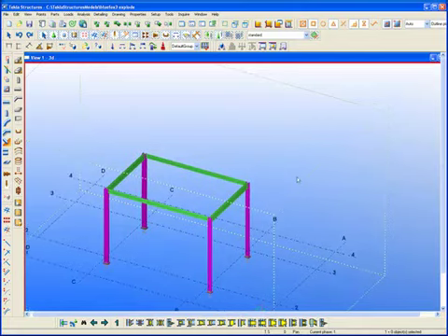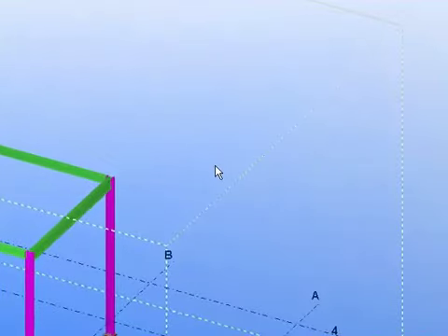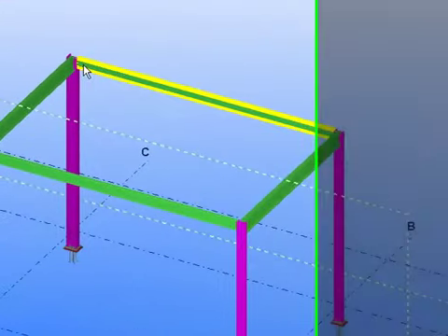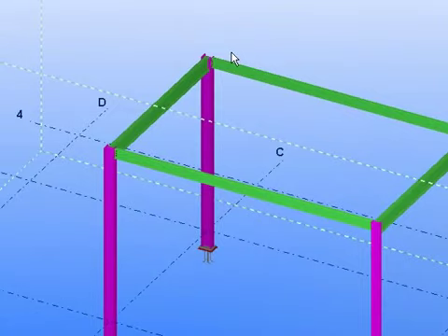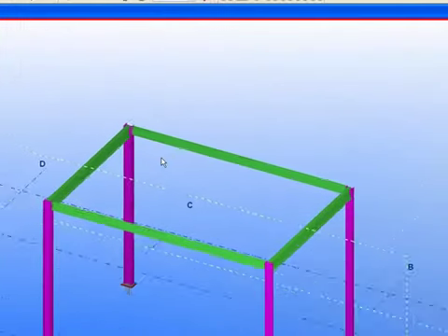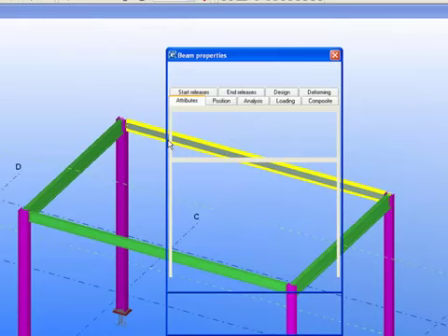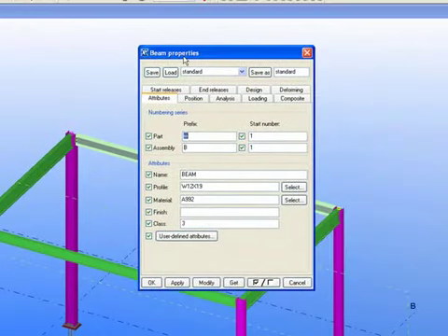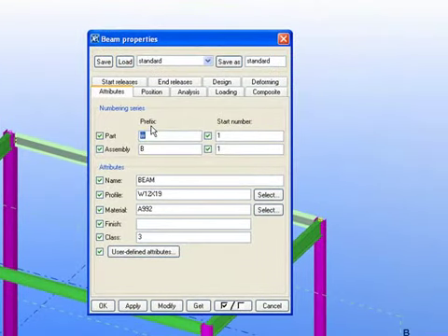In this short lesson, I will show you how to put assembly number marks on and do a numbering. If you double click on any member of the steel in the model, you will have four places to input the mark. You will have part prefix, part start number, assembly prefix, and assembly start number.